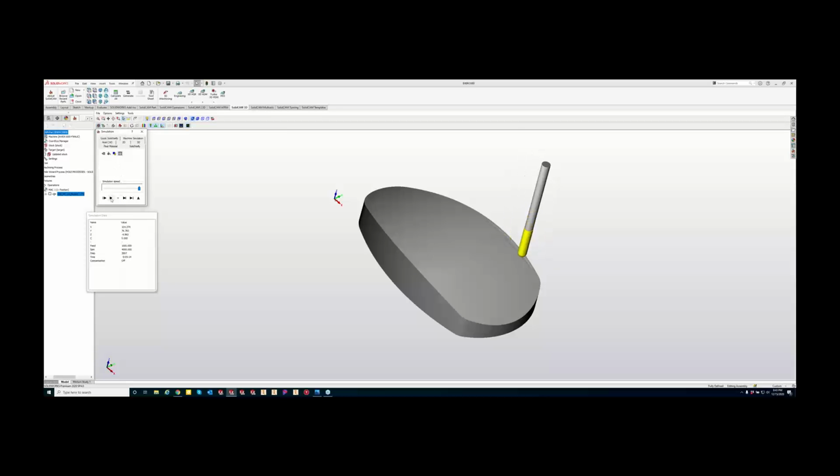Actually, now, one thing to keep in mind is if you are tightening up that step over as the last step, definitely be aware of the links selection, because if you're closing up the gaps between slices, that could change some things from a large gap to a small gap, and thereby change your selection. So if you do tighten things up, just take a look at your links and make sure they're still doing what you want.